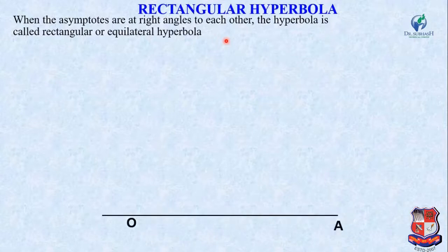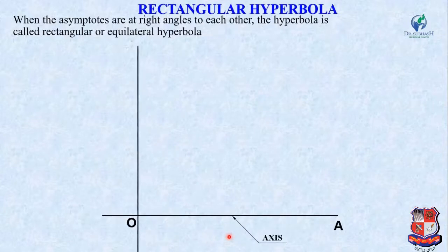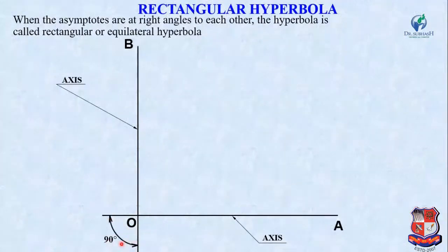So for that, if the two coordinates x and y are given, then first of all draw an x-axis OA. Okay, this is the axis, and another axis OB. Both are perpendicular to each other, at a 90-degree angle. Okay, now as per the given data, mark a point at a distance of x on this axis OA.